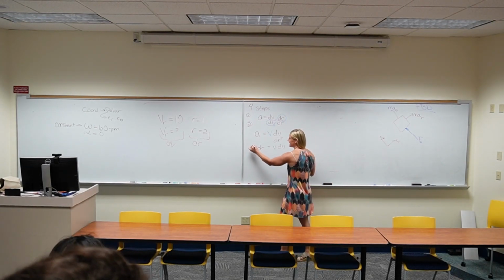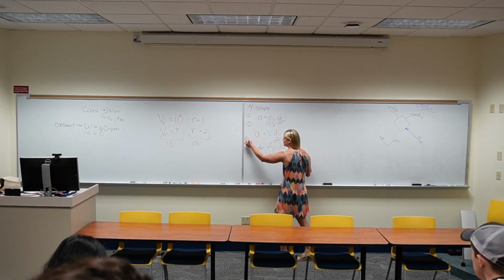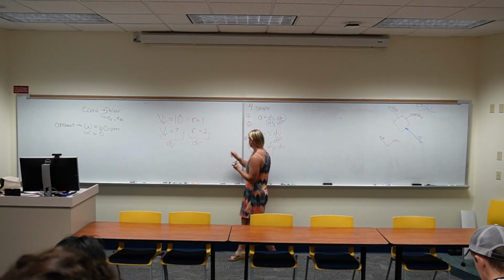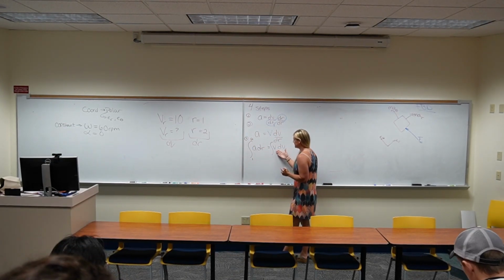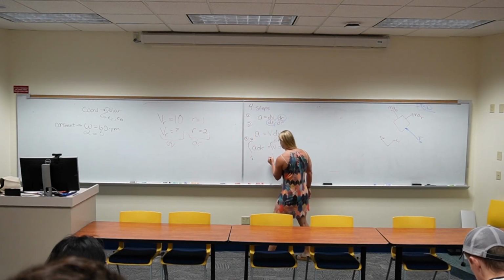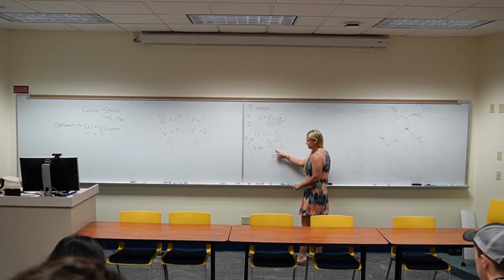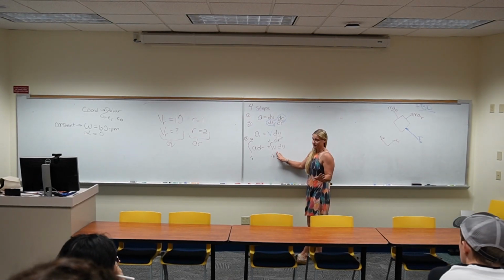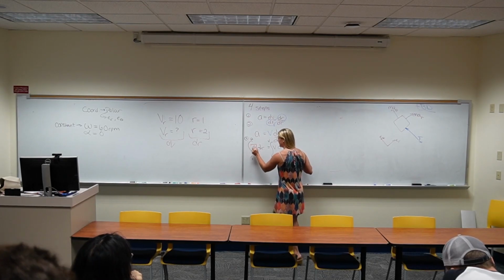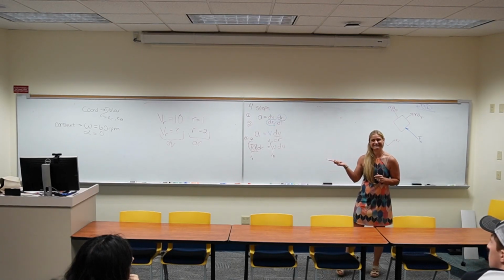So now I can integrate, which is step 3. I can integrate my acceleration with dr, and we said my limits are from 1 to 2. And I can integrate velocity, which we said was from 10 to v, which I have to find. I'm looking for v, so I can keep that as a variable, no big deal. This side of the equation I am totally fine with. This side of the equation, I don't know a. Now how am I going to find a?